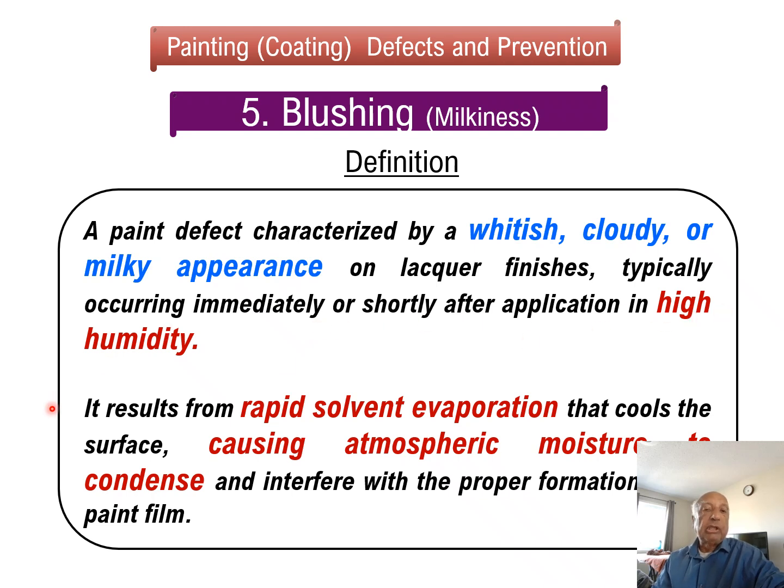It also results from rapid solvent evaporation that cools the surface, causing atmospheric moisture to condense and interfere with the proper formation of the paint film,